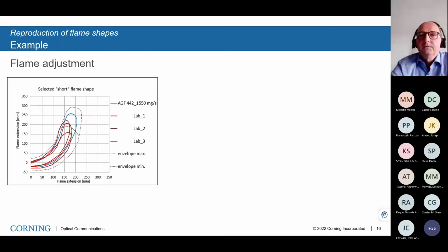So far, we have not found a parameter setting within the allowed tolerance range which has led to flame shapes out of the accepted envelope with remarkable influence on the flame spread. Further investigation should explain a correlation between a short flame shape and a low flame spread.